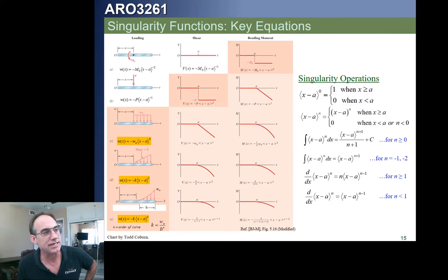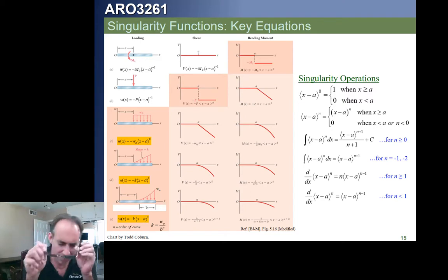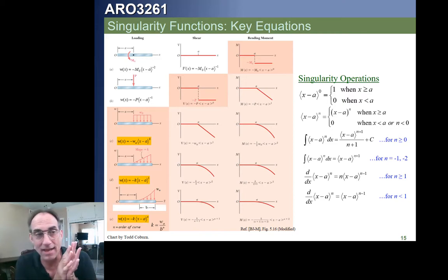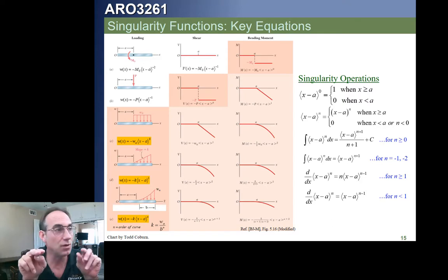Now, actually, you can use this also to jump over to bending moment or shear and just grab those functions as well. However, because the integration is so simple and because repetition tends to make us make fewer errors, I recommend sticking with just writing the equation for the loading here using only the first column, integrating once using the integration procedure here. It's rather simple. Integrate again, then we get the shear and moment.